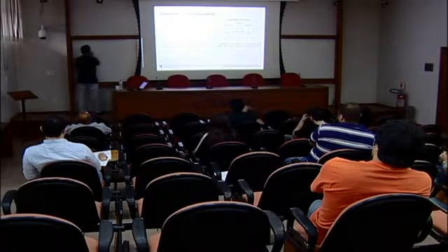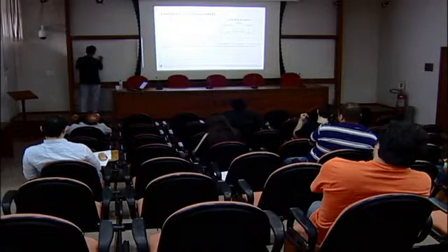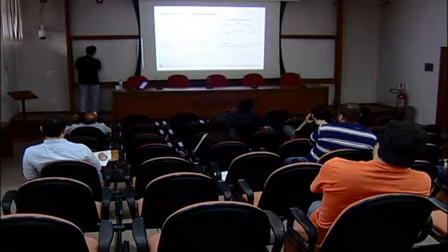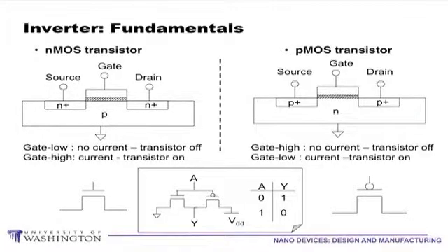So we have this N-type material. These two N wells are installed in a P-type semiconductor, silicon. And there is a dielectric membrane in there, so there is no direct current between this aluminum layer, the electrodes, and the P-type semiconductor.